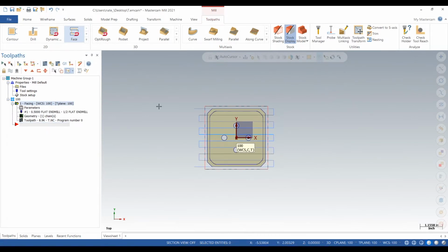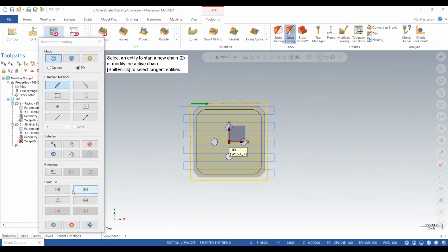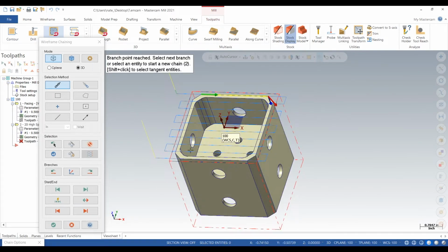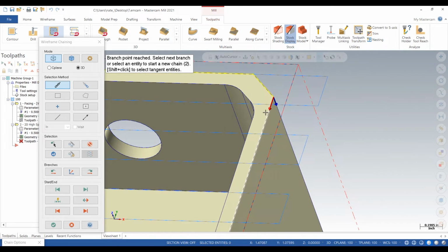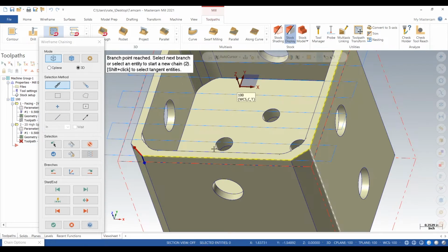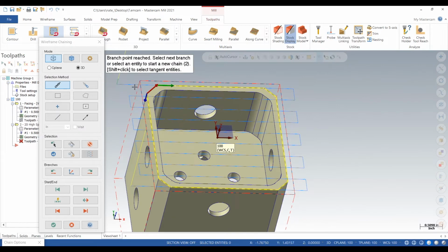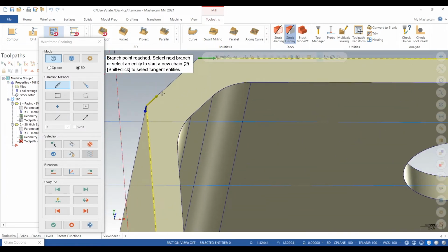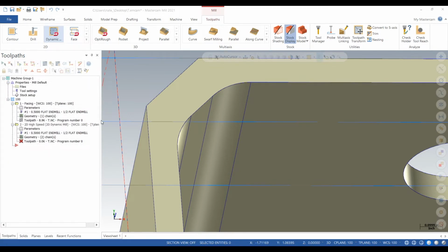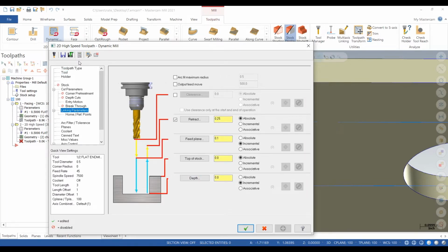Okay, that looks good. Next, go to dynamic, machining regions, click on that stock we created. Avoidance regions, let's click on the profile, the outer profile of the part. You can use wireframe or you can just use the solid geometry. I always just create wireframe so I have the option. So we'll just click on the wireframe here. And the depth,